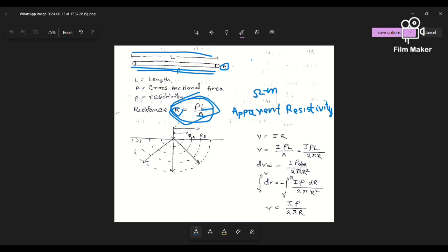In the ERT test, one electrode is placed on the ground surface, and it will generate current from batteries. The current will dissipate through the resistance of the material and create hemisphere-like resistivity.